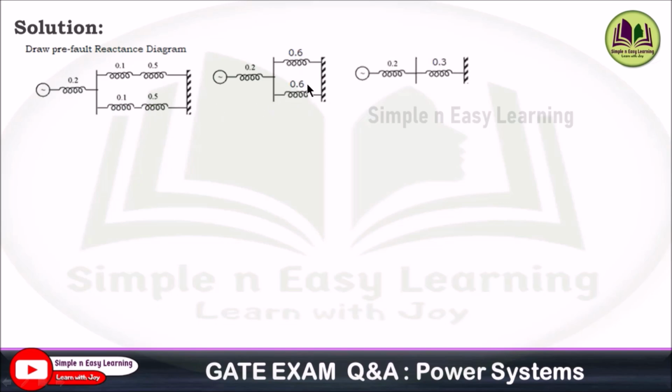Now this parallel combination of 0.6 and 0.6 becomes 0.3. Now we can add these two in series, 0.3 plus 0.2, we get 0.5. So the equivalent reactance is 0.5, X equivalent equals 0.5 per unit.